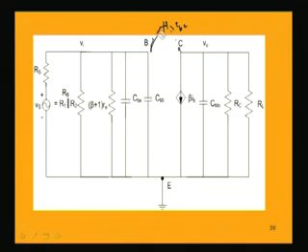So, what will be the value of these capacitances CMI and CMO, or rather what will be the corresponding reactances or impedances offered, that we can calculate. Others are all the same. CBE is already there and it is not creating any problem since it is between base and ground. The problem was created by CBC, because it was shunting between these two and we were not able to analyze the circuit because the input and output sides were not separated out, so we will have to use this technique.